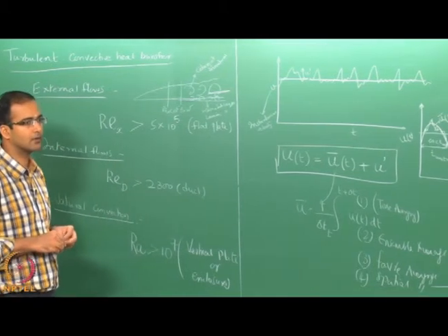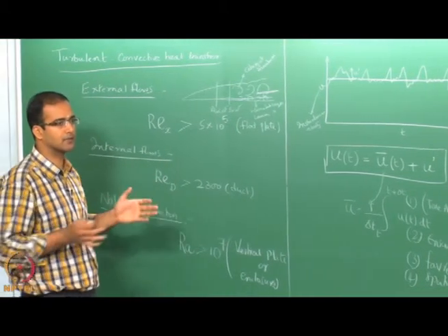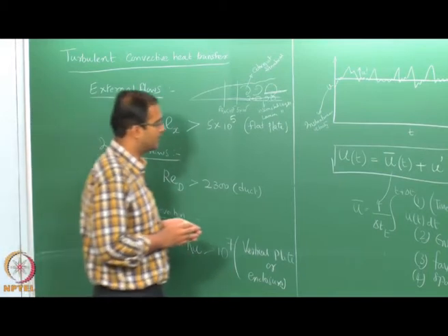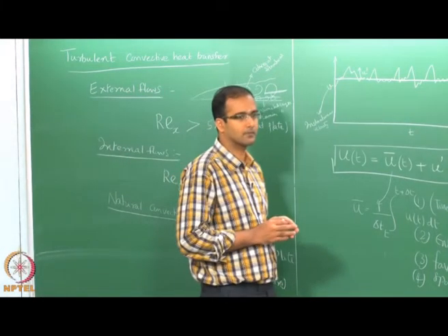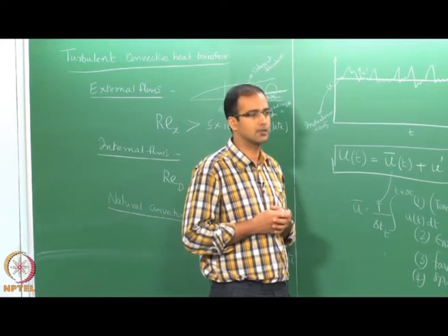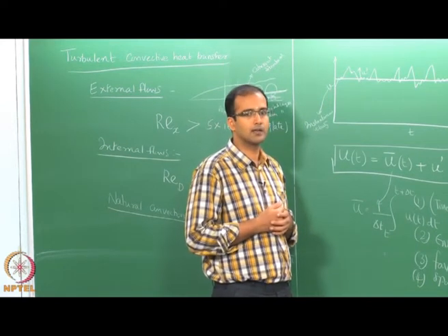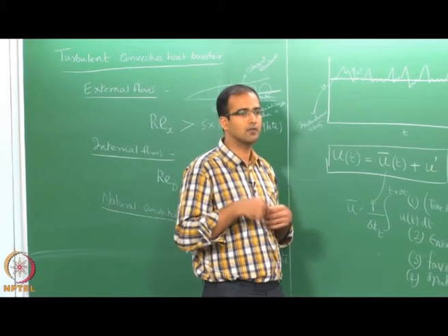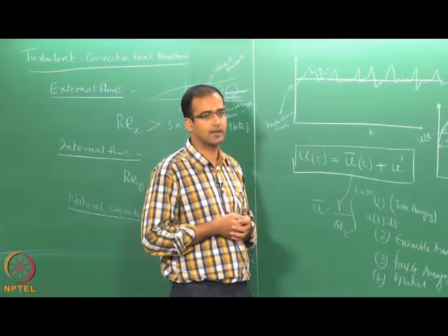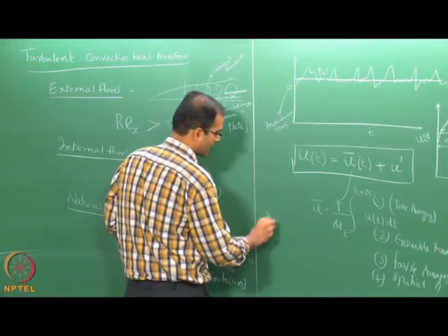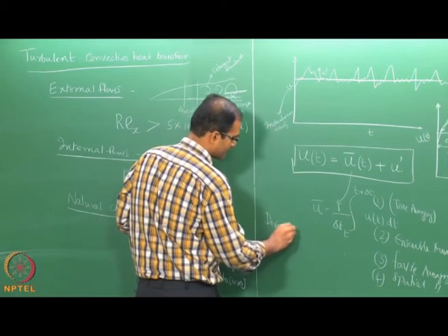For this, in the most generic case, we solve the Navier-Stokes equation as it is. When you solve Navier-Stokes as it is, meaning there is no analytical solution to that, we only do it numerically, but we use a grid size which can actually resolve all the length and time scales. This kind of treatment is called direct numerical simulation.